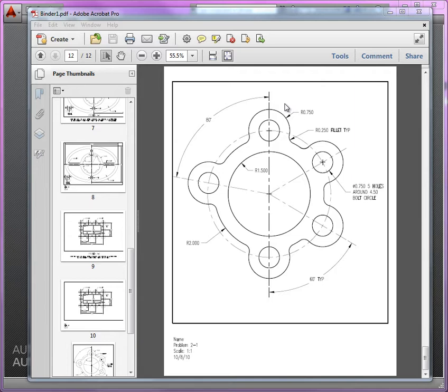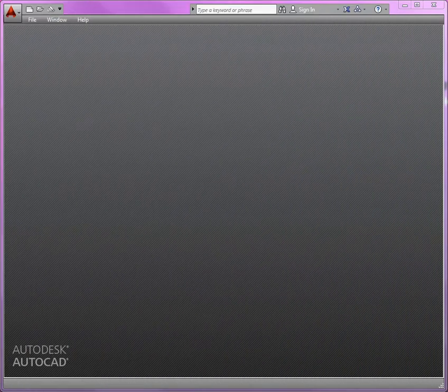Now the scale that's shown here is suggested, so please try to limit your selection to the A-size portrait or A-size landscape when you do your presentation. Make sure you include your reference lines, all your dimensions, and that you set the appropriate scale for the viewport and annotations. Alright, so what I'll do here is let's get started with a brand new drawing.